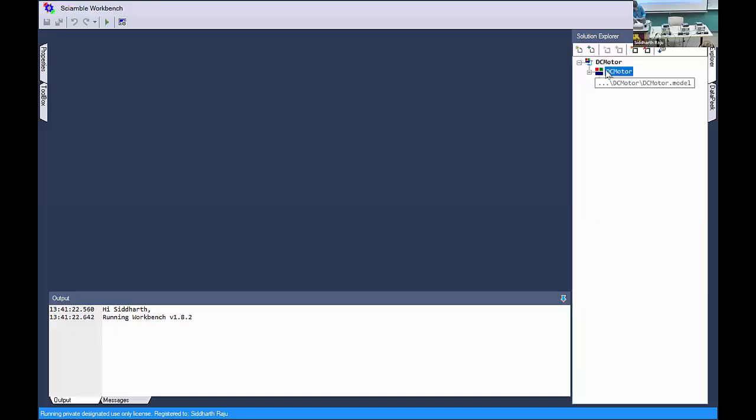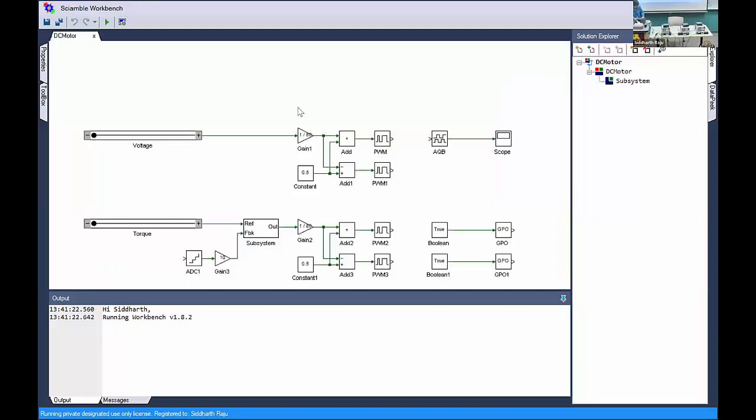So the model that I have here, this top part is what is controlling the voltage for the motor. When I slide this voltage, it is basically telling the two legs that I drew here, right? So for these two, if I give a PWM of 100%, then the top switch will always be on. If I give a PWM of 0%, the bottom switch is always going to be on. Right? So that's all this block is doing.